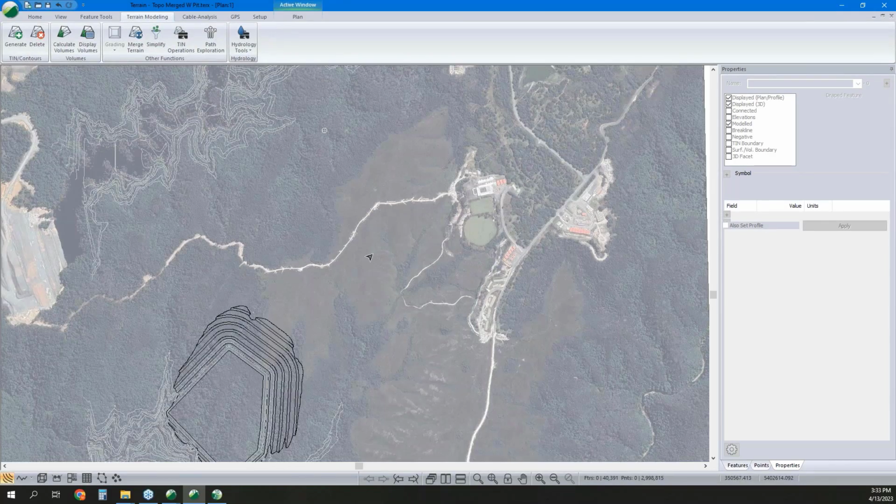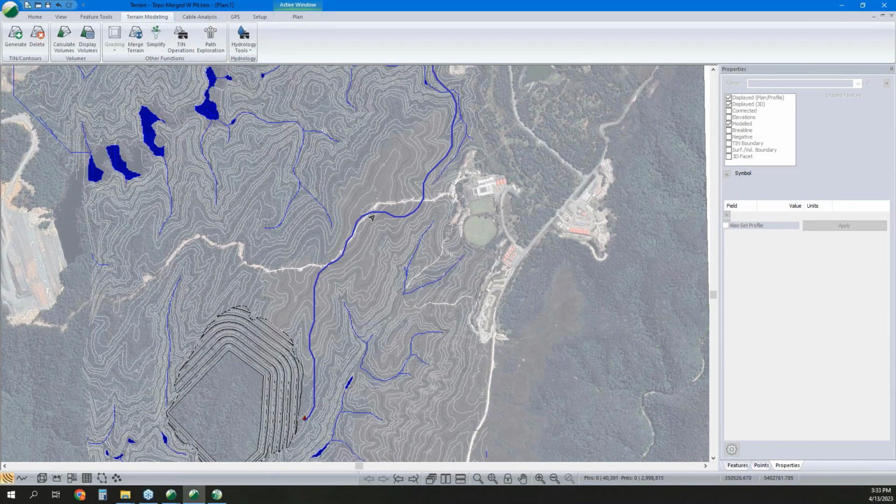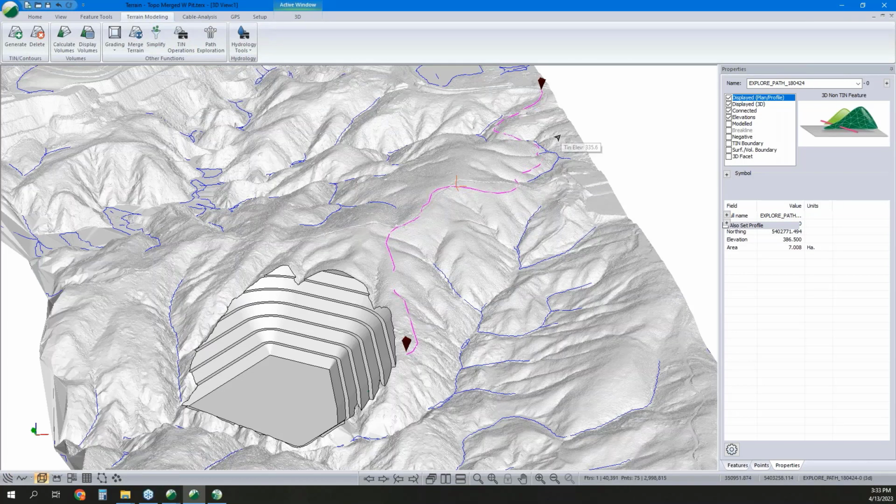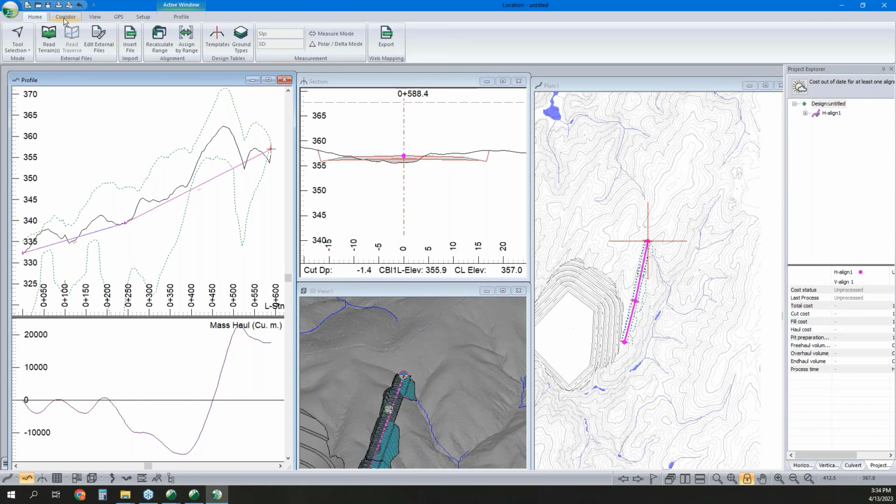Okay. I've got it to run a single iteration here, and it's telling me that this is a good representation of where to put my road when I'm designing it. A couple things that I've done in the background previously, I've got some penalties applied to things like streams and areas that I don't want to go. So it's taking that into account as well as my earthworks costs to get from point A to point B. I'm going to just switch the terrain file that I have referenced.